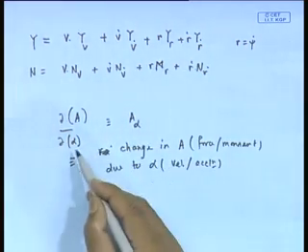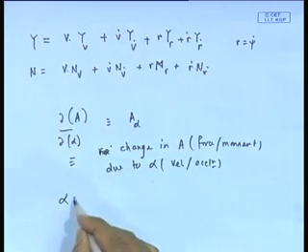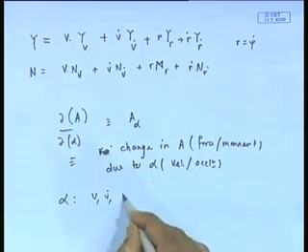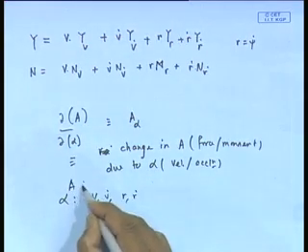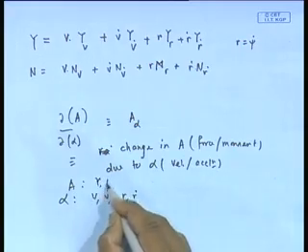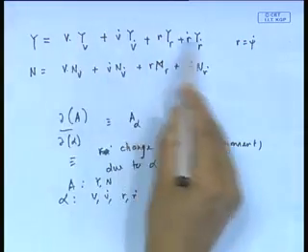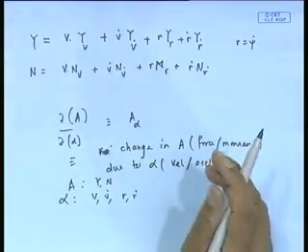So you have basically 4 motion variables, v, v dot, r, r dot, and 2 equations in this case, y and n. So they have got a total of 8 such terms. These terms are called hydrodynamic derivatives of the hull, linear hydrodynamic derivatives.